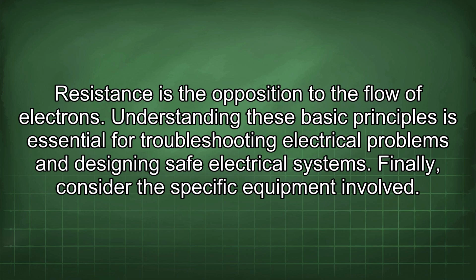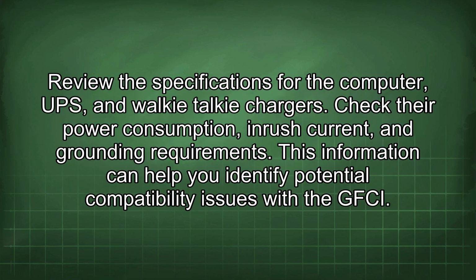Finally, consider the specific equipment involved. Review the specifications for the computer, UPS, and walkie-talkie chargers. Check their power consumption, inrush current, and grounding requirements. This information can help you identify potential compatibility issues with the GFCI.